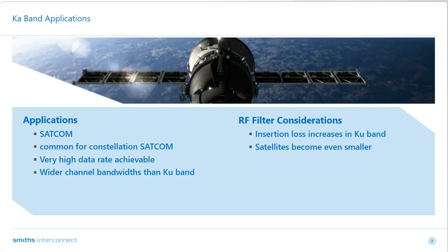Finally, I will discuss the Ka-band applications, and a large segment is again found in satellite communications. There are discussions on the proponents of Ku versus Ka bands for SATCOM, with valid points to be found for both. One factor to consider is the higher attenuation due to rain fade. This signal attenuation is compensated by additional power, so many times the uplink, or terrestrial to satellite transmission, is Ka band, and the downlink, or satellite to ground station transmission, is Ku band. The additional power to transmit to a satellite is obviously more readily available on Earth.